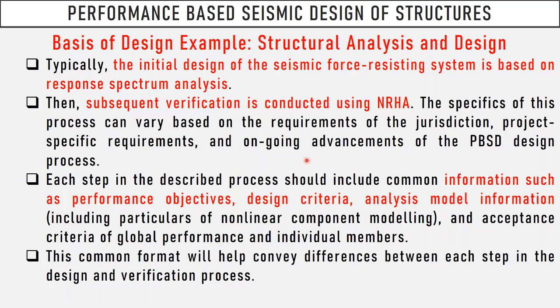And of course, starting from the first point, you will initially make a response spectrum analysis, and you are going to verify your design with nonlinear response history analysis. Based on the nonlinear response history analysis results, you may change your design, your section dimensions, your capacities and so forth.